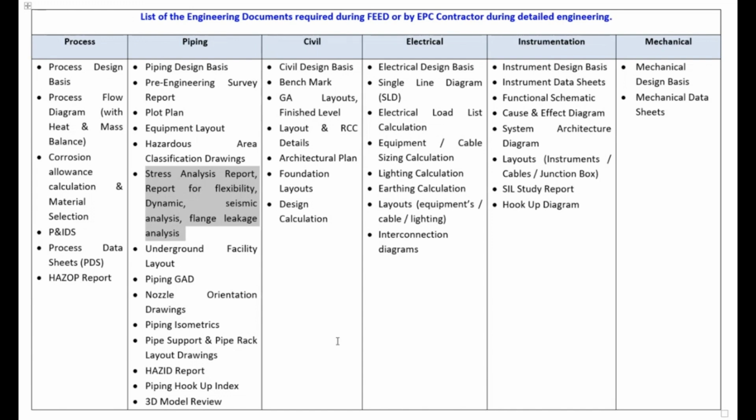But within the design limit of compressor vibrations, whatever vibrations are getting transmitted to the piping, inlet piping, outlet piping, that piping should not crack, okay? The flanges should not crack, okay? The joint should not snap, okay? So all these studies are done on the piping system. This is one of the critical analyses because safety is paramount. So this is what is being studied here.